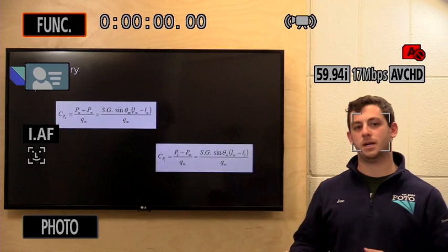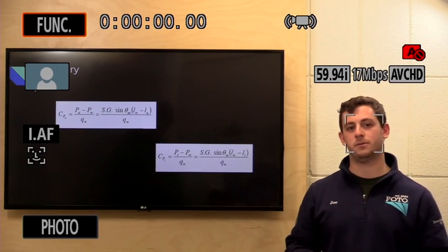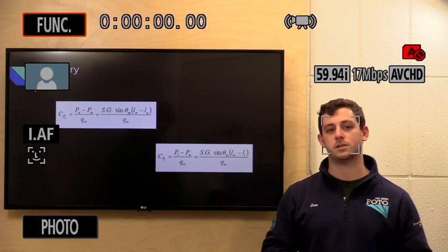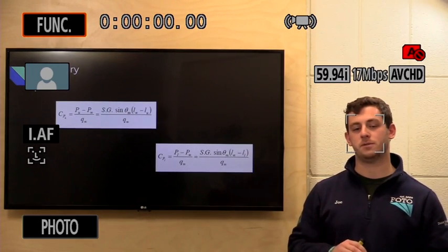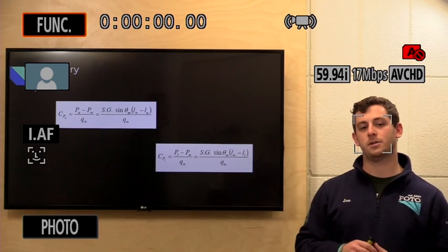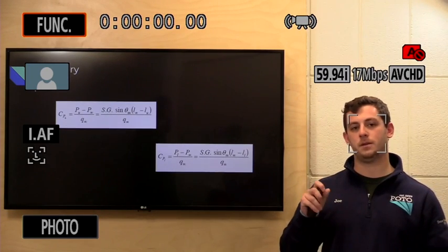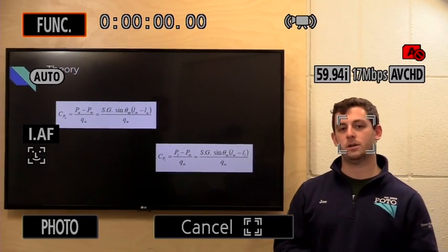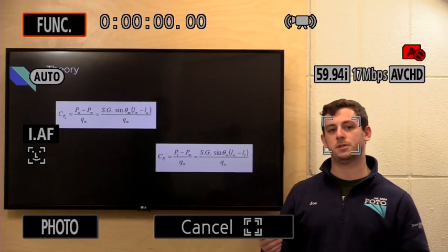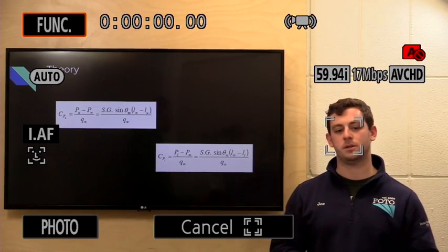So the first step was to look at the pressure coefficients across the surface of our airfoil. We have to separate the upper and lower surfaces of the airfoil and look at individual points across each surface of the airfoil. So each equation here represents an individual point on either the upper or lower surface.